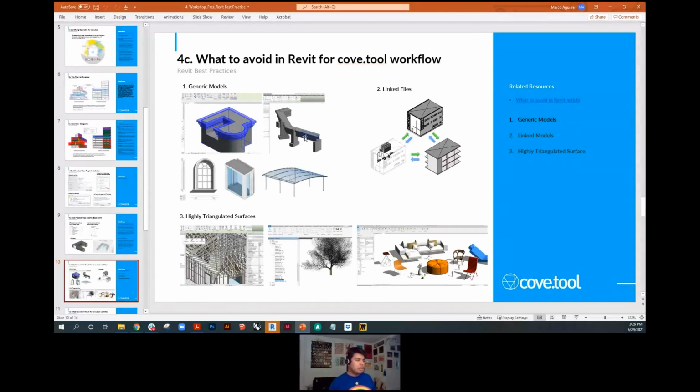Generic models are created vastly different from the rest of the geometry in Revit. They're volumetric forms that don't have centerline information, and the centerline from every object is what the plugin is searching for in order to recreate it. So if it can't find information like area and coordinate points when attempting to export, it's going to skip those objects. Typically this is associated with generic models that you didn't create yourself, or that aren't just simple extrusions, but much more complicated.